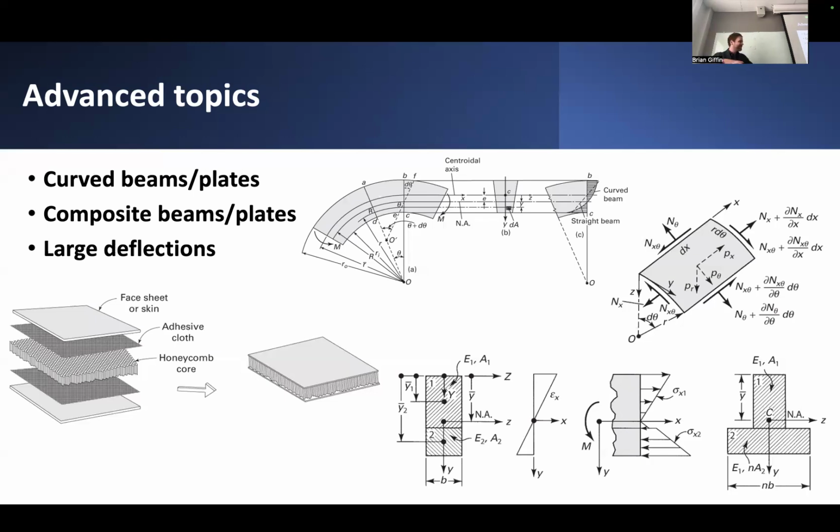So even if you did all the other things to try to account for these different things, dealing with the issue of what happens if these plates or beams undergo relatively large transverse deflections, in those scenarios, you kind of have to invoke some different assumptions as to how you even construct the whole theory. Because Euler-Bernoulli beam theory and Kirchhoff-Love plate theory really are centrally predicated on this assumption of small deformations. But if you introduce the possibility of large transverse deflections, large displacements, then it gets a lot more complicated, trust me.